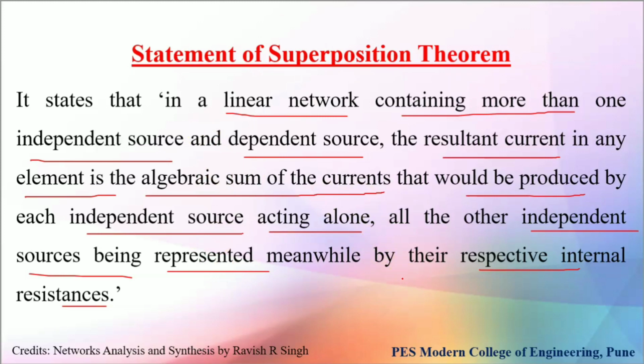While applying superposition theorem, we have to remember: if a voltage source is there, then we have to short it, and if a current source is there, we have to open it.